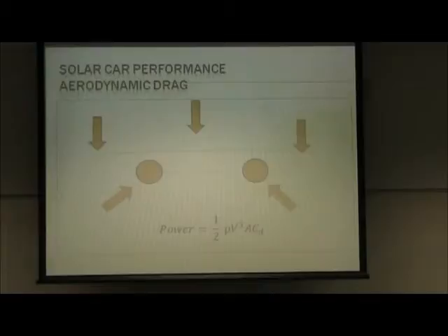If humidity, it's lower. Humidity, it's actually lower because H2O is lighter than nitrogen and all that other stuff in the air. So it actually gets better if the humidity's a little higher. Strange. Not condensing humidity, not rain. Okay, anyway, you've got that, and of course when you're at higher elevation, it goes down. And this is actually a significant enough effect that you want to model it in your model. You want to know the current air pressure, temperature, and humidity to come up with a model for that.